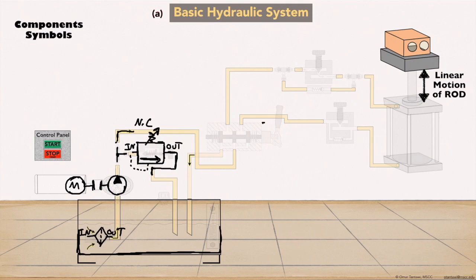If the oil did not reach the maximum pressure, then we have a flow all the way to the DCV, the direction control valve. The direction control valve has 3 positions. If the handle is pushed all the way forward, then I'll end up with the extend position.